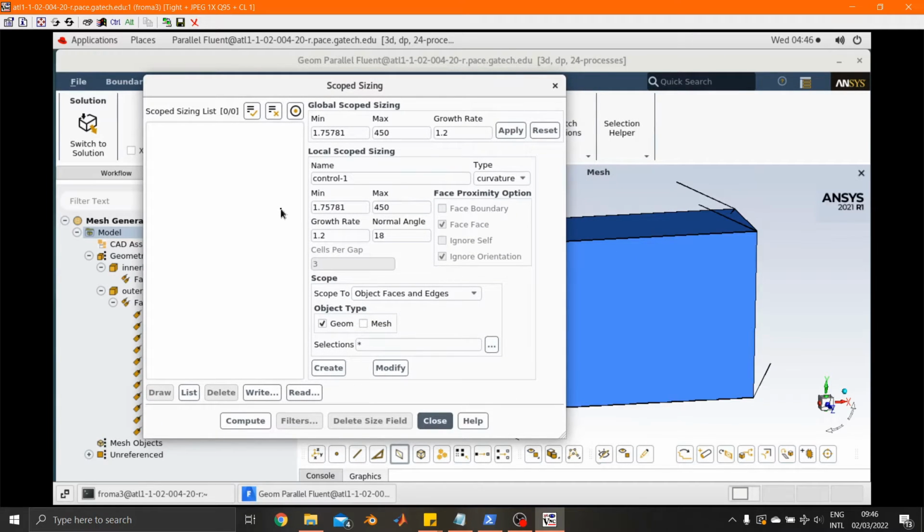faces. So we're going to begin, because the reason we created the body of influence is this is why. We're going to begin by setting general sizes for the body of influences. So that's going to affect all of the mesh cells inside each of our respective inner and outer BOIs. So the first one we're going to add is we go to Type, select BOI, which is body of influence. And we'll start with the outer one first. So we'll name it something like outer BOI.